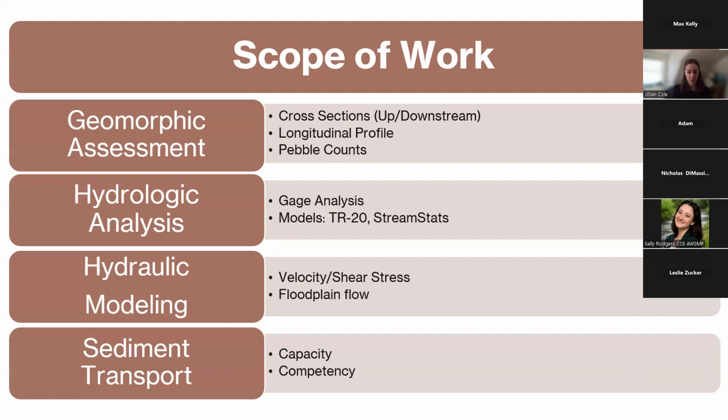definitely provide better results. And then finally, sediment transport is one that can typically be missed, but is very important to the structural integrity. And depending on how complex the site is and what data is available, this can be done from a more qualitative perspective, all the way up to a very detailed model that can be completed to analyze the sediment transport through the reach and the crossing.